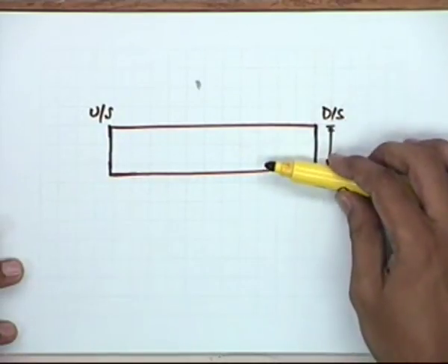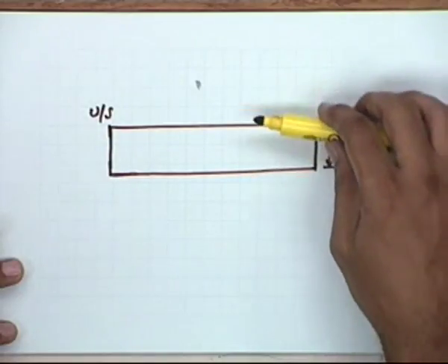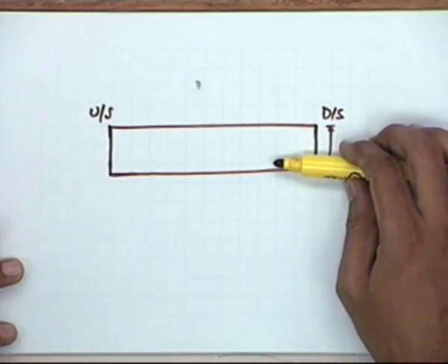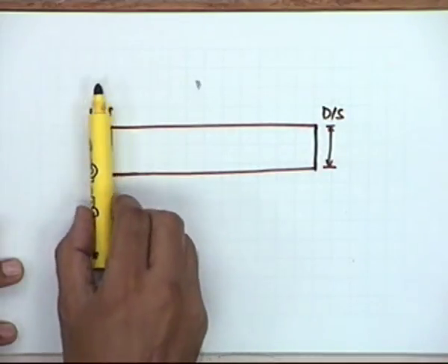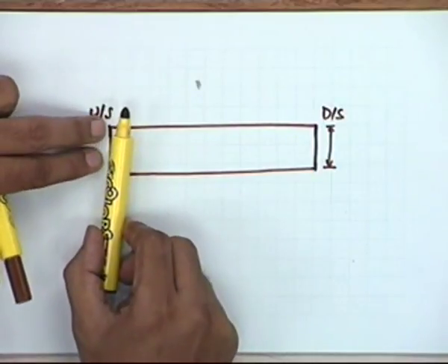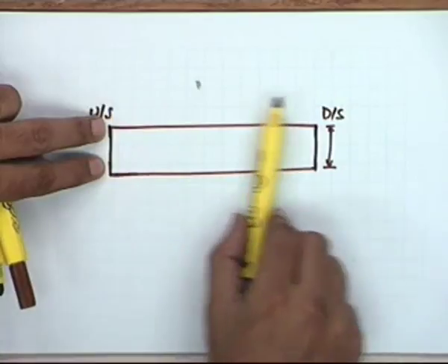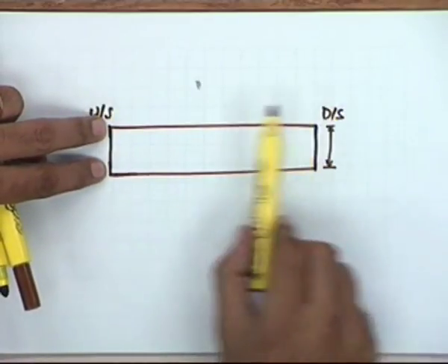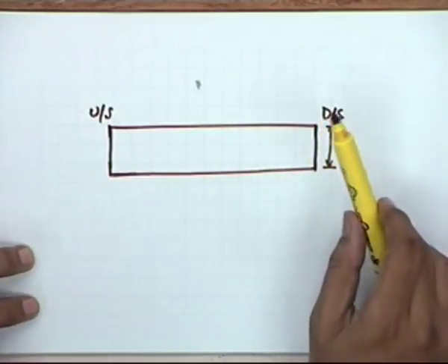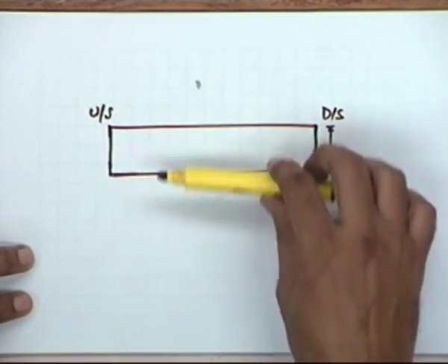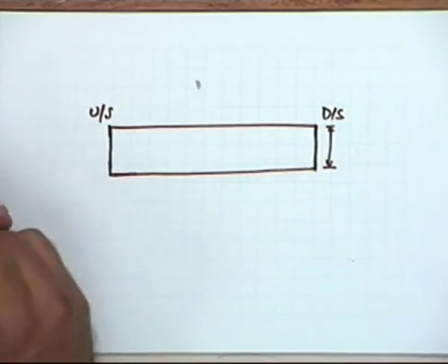So, this is the deficit which is created, and you want to satisfy this deficit. You know the total volume requirement. But if you provide that volume at the upstream end, how this volume of water gets distributed along the total length of the field matters. Unless it gets distributed in a way that you have minimum variation, it is not of much use.